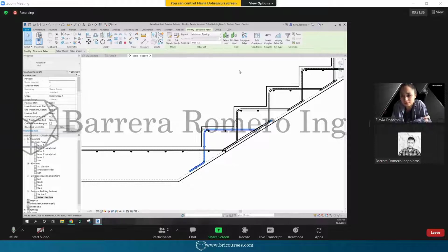It is very important to do that, because if you have a lot of different rebars in columns and beams all over the floors, it will be difficult for the contractors and the workers, because there will be some kind of mistake. If you complicate the rebar, you complicate the workflow, and surely that will lead to errors.